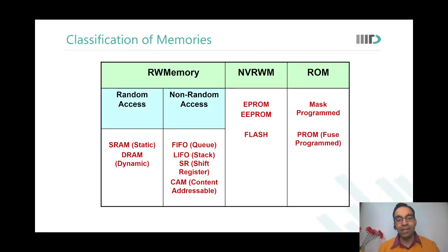Yes, sir. For that, we need to keep some buffers. Those buffers are usually first in, first out kind of buffers. Whatever data was written onto the bus first will be stored, and then that will be pushed on the bus first. The data that comes afterwards will only be pushed in the second cycle, and so on. So that is first in, first out. This is the queuing mechanism which you would use in clock synchronization across two different domains.